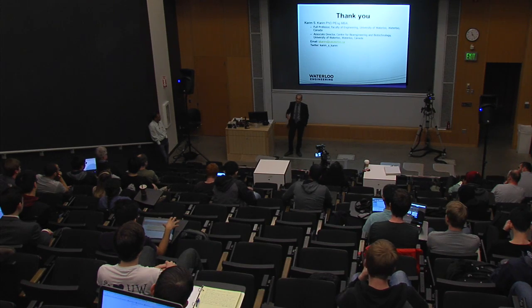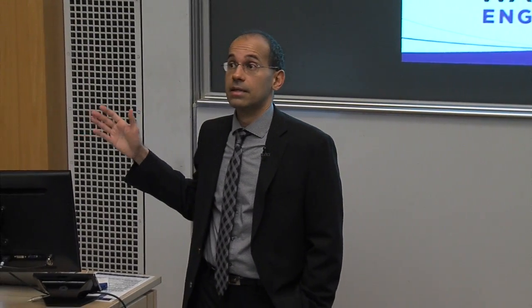Right. So in this case, our limitation is not set as much by the pixel sensor. It's actually set by the readout electronics that are supplied from external vendors like Analog Devices. The best cycle times they can do are, I think, line times of 22 microseconds, which translates into something like 30 frames a second for a fluoroscopy-capable 30 by 30 centimeter imager with a 150 micron pixel.